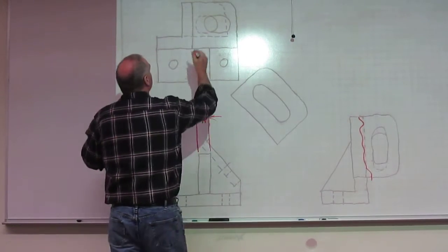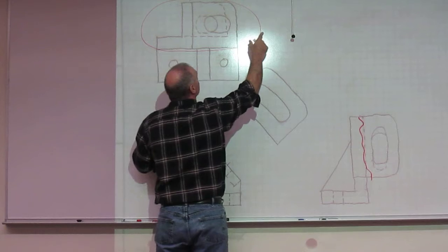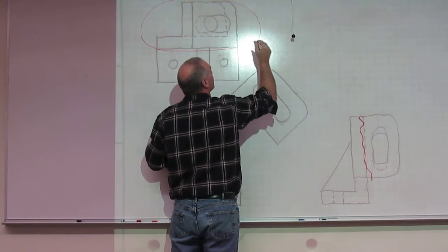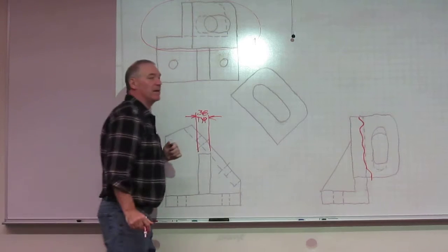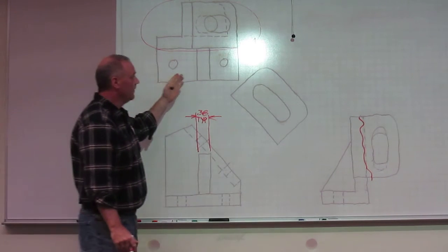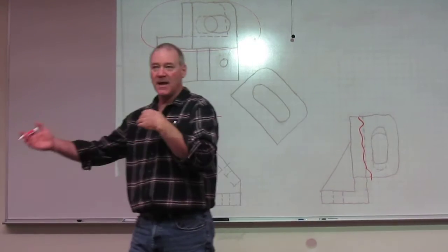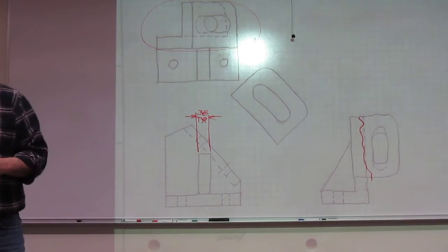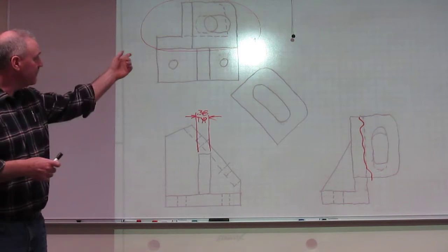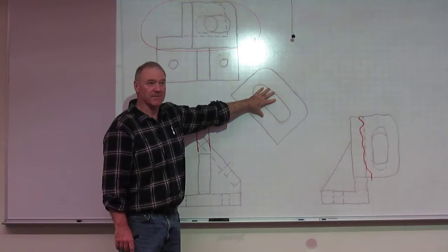They used the wrong line type, but we would use a phantom line, something like this. We would then interject a letter in there saying that it's a removed view, then pull it over. This needs to have a title that says View A. And then we're showing that in a different orientation. That's certainly something we do. I think it would be my second choice if I couldn't make this work first.